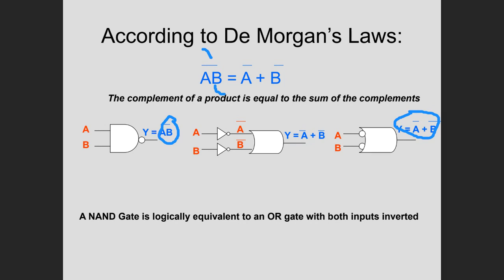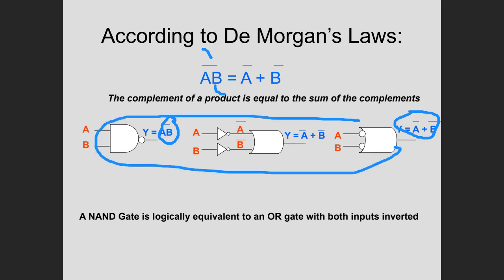So then you don't have to understand any of that down here. If you look at this and say, all right, I want to demorganize it, I'm going to break the lines. That means each individual variable, the line is broken. And then whatever the sign is here, if it's a dot, I'll change it to a plus. If it's a plus, I'll change it to a dot. And then this will be demorganized.